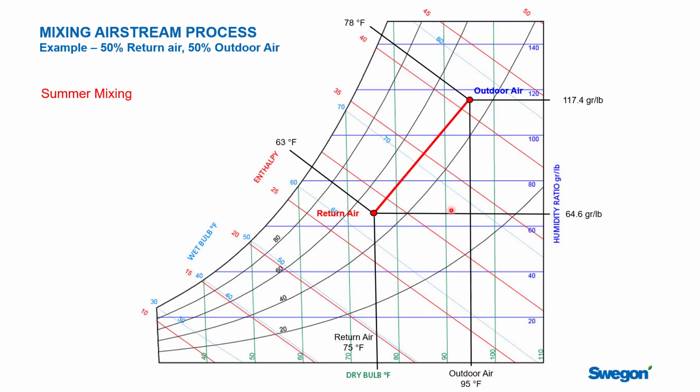It's very warm. And then these 45-degree style sloped lines here that you see, the blue ones, the 70 and the 60, this is the wet bulb. And so you'll often hear outside air described as being 95 dry bulb, 78 wet bulb. And once you have two properties of air, you can plot yourself on the psych chart. You can see we position ourselves right here, knowing these two conditions. And you'll see that we've also called out another one with this horizontal line.